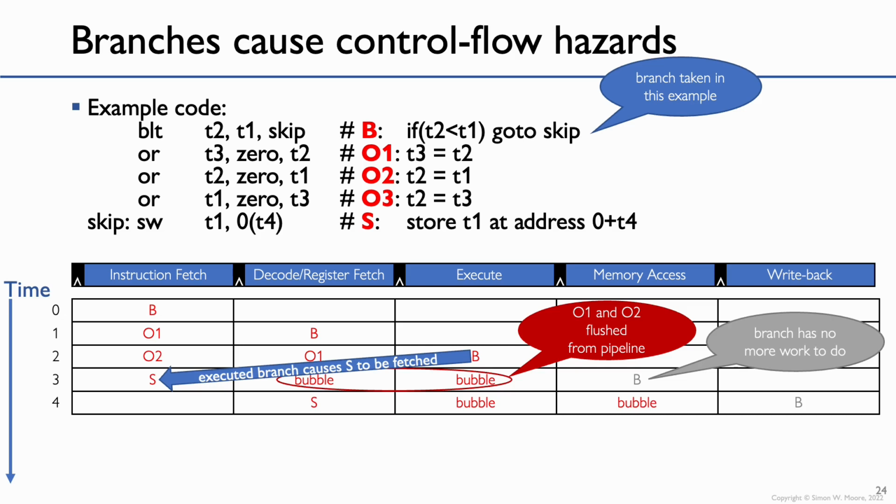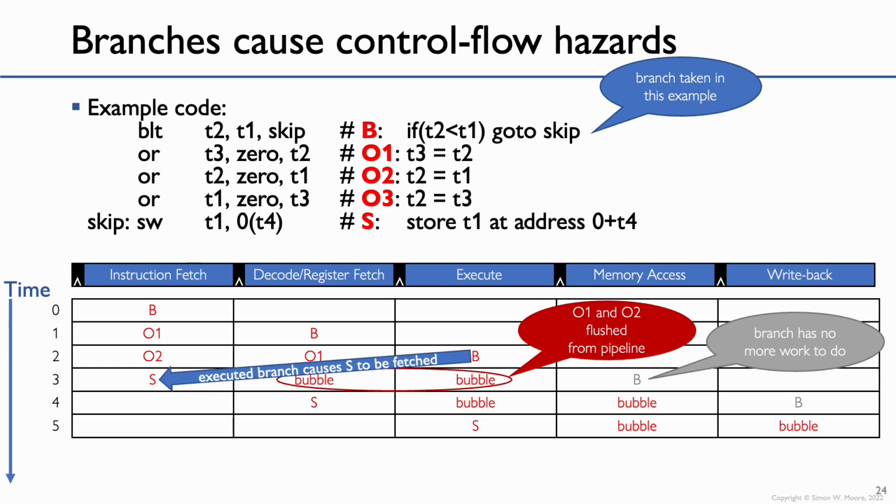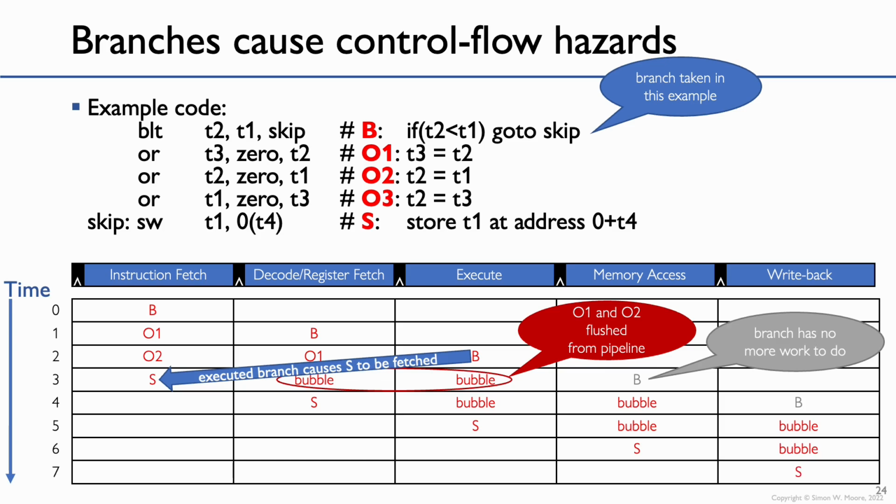Okay, so in the next clock cycle, the S instruction proceeds to decode, and of course we've got those bubbles in the pipeline, and then we basically just allow that to proceed until the S is finished and whatever instructions follow it.